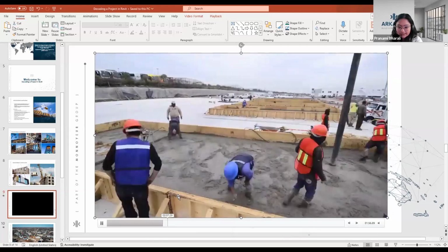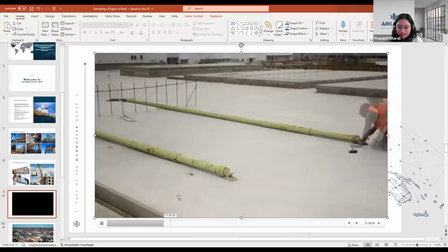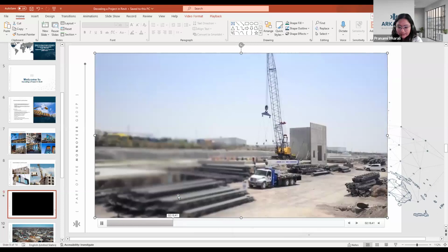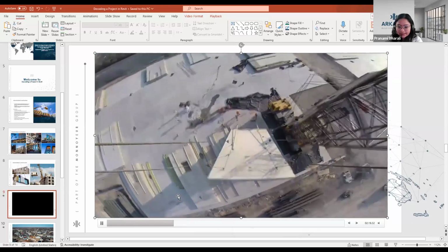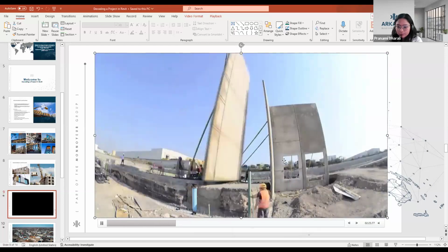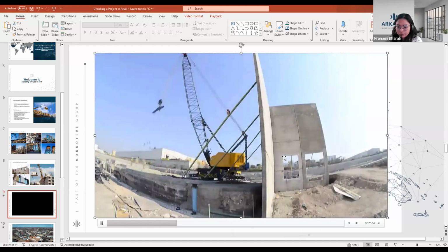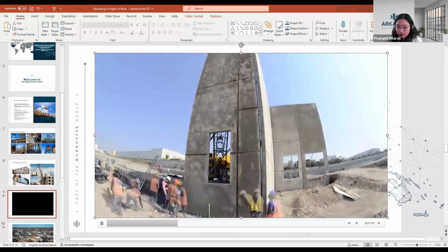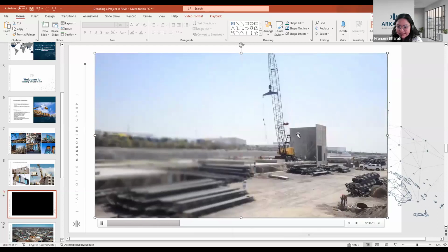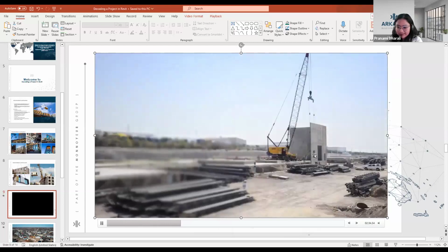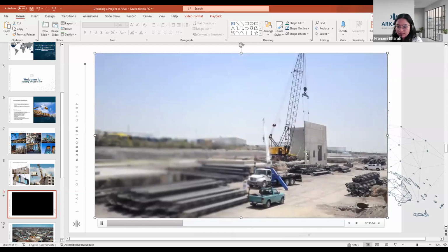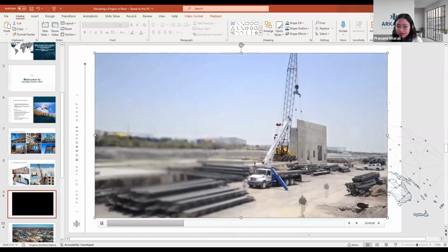After the foundation is cast, in the factory, you will be seeing, these precast walls are made. The walls with appropriate window spaces, door spaces and everything are made, and these are directly transported to the site, as you can see, and with the help of a crane, they are installed on the site, right?